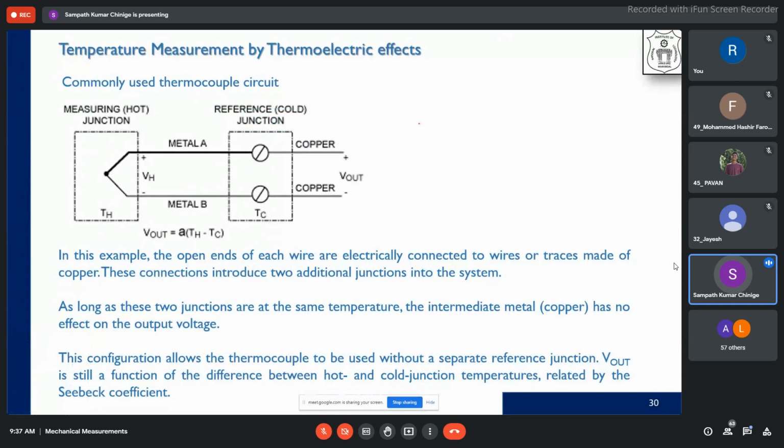So I bought one wire, which is having two wires inside. This is how the thermocouple is, and there is a sheath, a covering of this, like this. So inside two wires are there. For example, imagine that this wire is like this. There are two terminals like this. What I'm trying to do is make these two terminals into one simple bond. How do we do that? We do that by welding or soldering process.